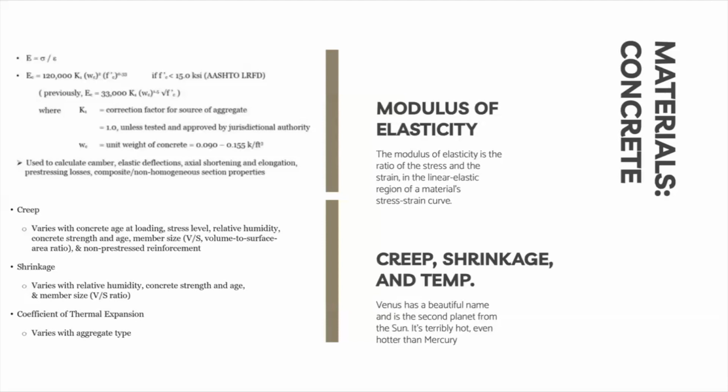Concrete's coefficient of thermal expansion, influencing its expansion or contraction due to temperature changes, is vital to designing bearings, connections, and expansion joints, with variations based on aggregate size, detailed in the PCI Bridge Design Manual, Chapter 2.